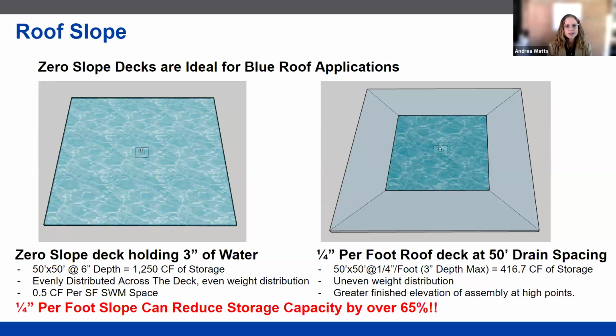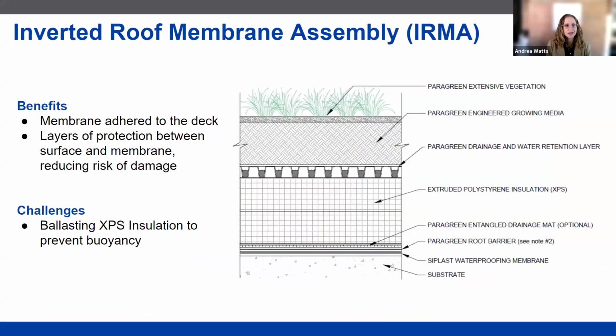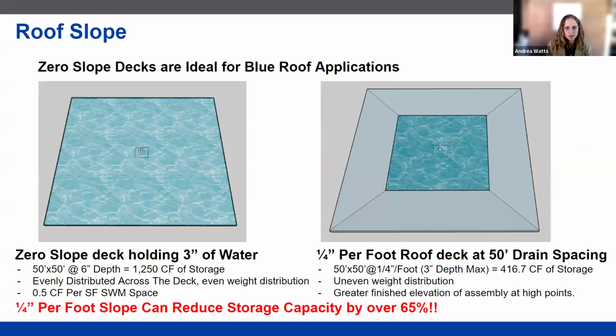It's also important to recognize that a flat roof is only possible when we're using a true waterproofing membrane. Single ply membranes, the thermoplastics and the thermosets, do not typically allow for application on a completely flat roof. They require integrated slope either from the roof deck or the insulation in order to allow the drainage. They just can't handle being that bathtub. So again, it goes back to choosing the right product for the right application.